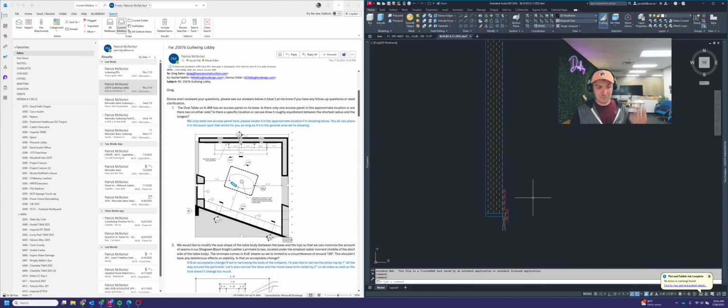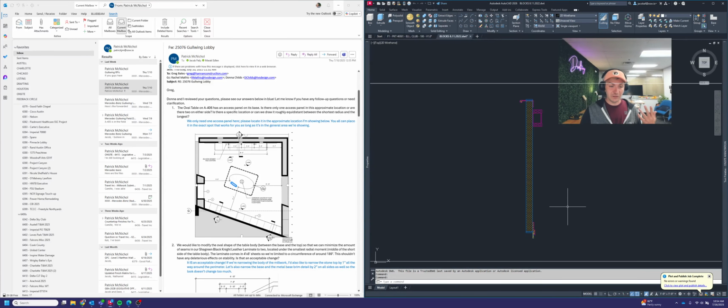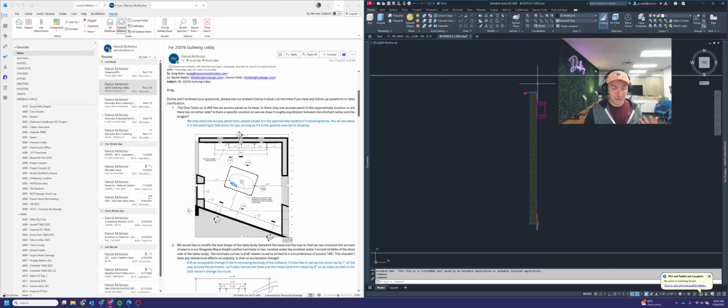If not, this is what it'll look like on the inside of an access panel. Tab pull at the top, magnetic catch right below that, Z-clip at the very bottom. That holds that thing on, locks it in place. The magnetic catch just holds it up, and then the tab pull makes it easy for somebody to lift and pull the panel off that desk.